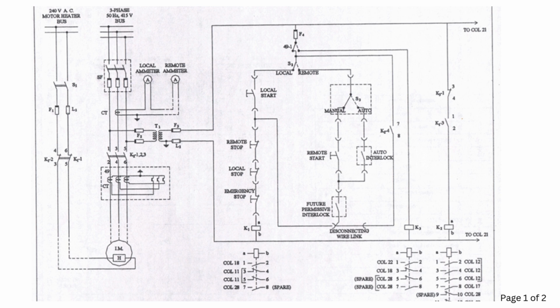The operator is available in the control room, which is at some distance, for the safety of the operator. An emergency stop button is installed in the central control room as well as the local location for safety purposes. When the motor is turned off, the interlocking circuit automatically switches the heater on to prevent moisture buildup. So in this case, we assume that the motor is in a plant where moisture is present, might be due to cold storage, or maybe some water is sprayed around the motor.